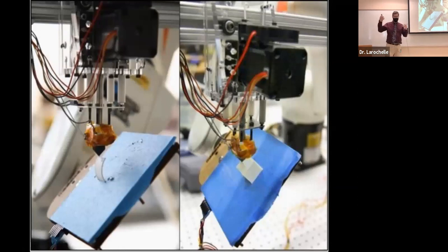One version of a Cartesian robot is a gantry robot. If a Cartesian robot throws you off, you understand what a gantry robot looks like, or even just a gantry crane in a warehouse, same kind of thing. Here's the printhead on the end of there. By using the gantry robot and moving this printhead in X, Y, and Z directions, they can print out a curved structure and a cubic structure like this, and not necessarily print in parallel slices to what we call the build plate or the build plane at the bottom. So they were able to make some nice contributions there.